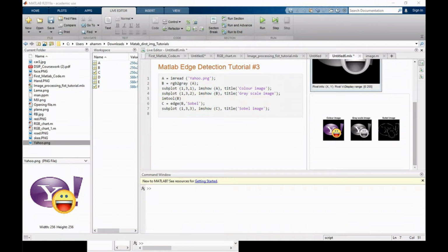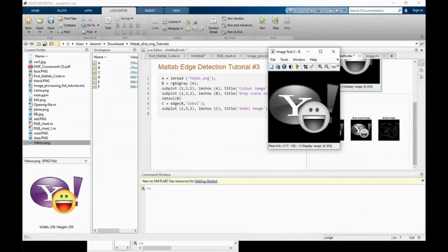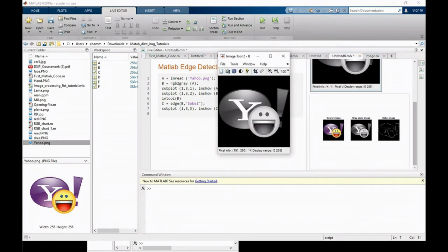As this place is not proper, there is a little bit of white, I would assume it would be 100 or something. What value is it? If I take the IM tool, so this is the picture. If I go here, the white is 255, 97. This pixel here is 216. This pixel, a little bit black, is 102. So that's how the edge is detected, and the command I have already shown you.